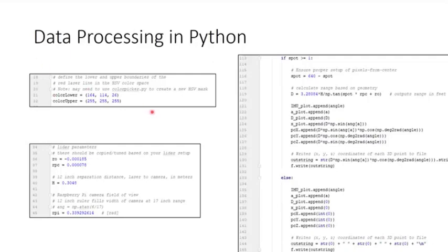On the top left is the code for the HSV mask that will be applied to each of the images. The provided inputs are the HSV code for red light. On the bottom left are the parameters for calibration used in the geometric calculation that determines the range for each return. They include the radian offset, the radian to pixel conversion, the separation distance between the transmitter and the receiver, and the angle for the camera's field of view.